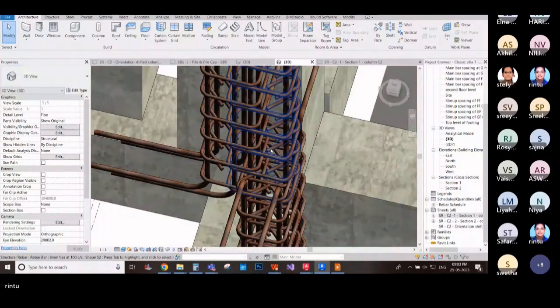To be a structural engineer, just designing on paper is not sufficient. You will have to come to the site and inspect whether whatever you design is being implemented. And for coming to the site and understanding what is done, you will have to visualize the same: where each bar has to come, what is the shape of the bar to be provided, what is the lapping distance, what is the minimum development length to be provided. All this needs to be familiarized and learned. Only then can you implement it properly on site.